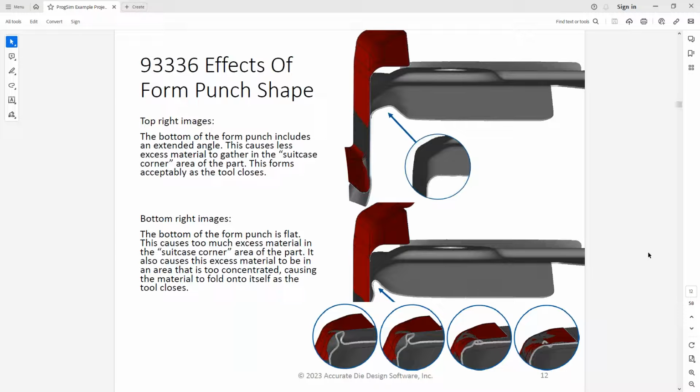Yeah, in fact, this one, Matt, in the top picture above that arrow, that pressure pad along that entire angular surface, the flat portion of it is a little bit shorter. Now if you go down to the next picture, that flat portion is longer, and that's why it caused it to bubble up so much more right there. If you look, the pads are in about the same spot. So again, there's so much that can influence it, and you're influencing it in minutes rather than in days, because otherwise you've got to cut metal and then try it, et cetera.